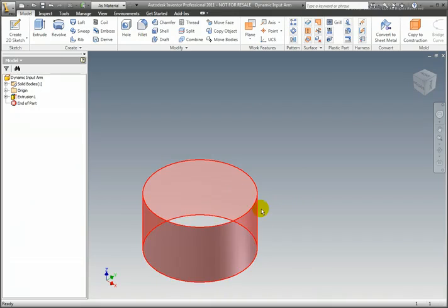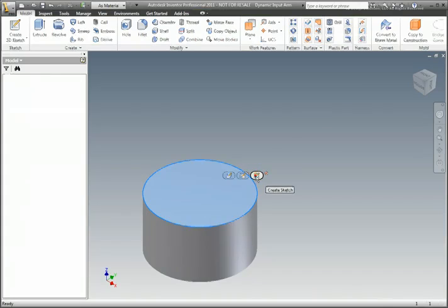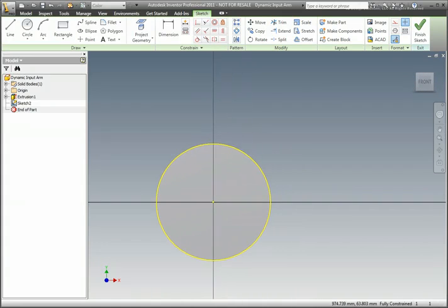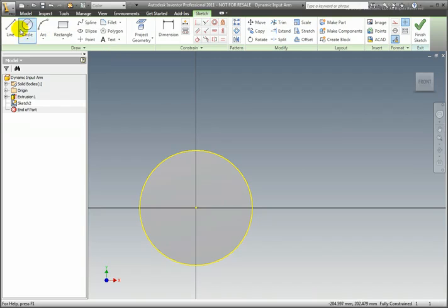Select the front face. Dynamic input displays icons Edit, Extrude, Edit Sketch, Create Sketch, and Close. Select Create Sketch. Select the Line command from the ribbon's Draw panel or press L on the keyboard for the shortcut. Start the line on the projected edge of the cylinder's lower quadrant.